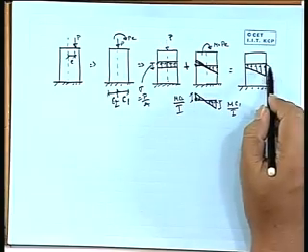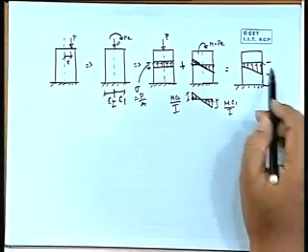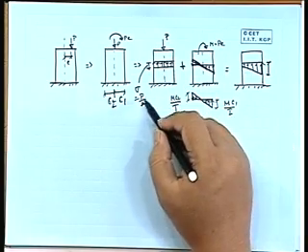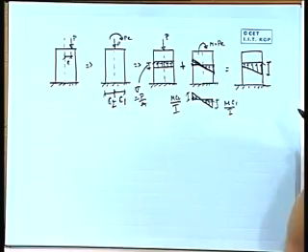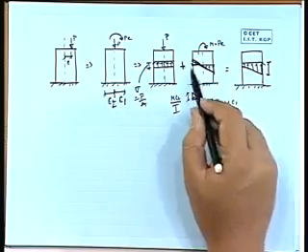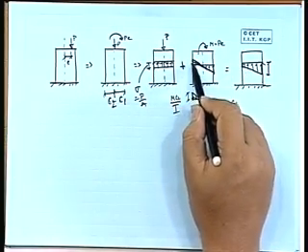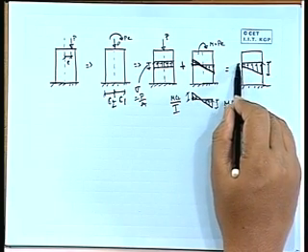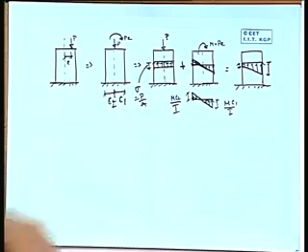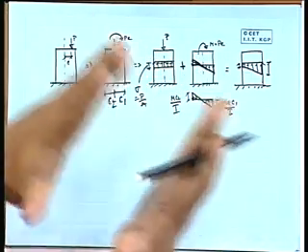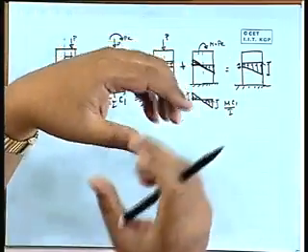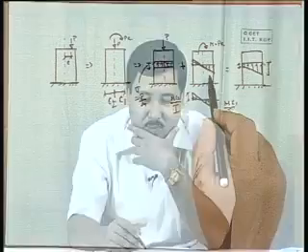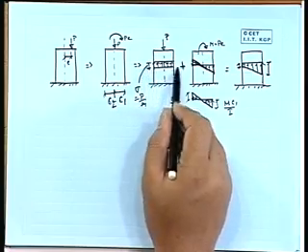Now if we add that, this stress will be how much? There is a stress M C1 by I, there is a stress P by A. So both will add together, and here this stress will be this minus this, it will be P by A minus M C2 by I, right, this small value. So due to the direct load, there should be a direct uniform compression, and due to the bending, it will also be a normal stress, one will be plus, another will be minus. So this side it will be compression, this side will be tension, here it will be entirely compression.